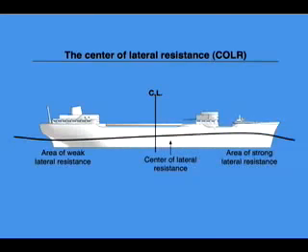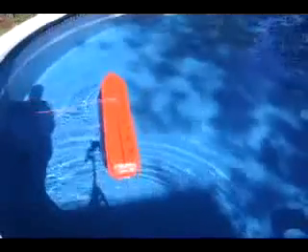This is mainly due to the positive pressure built around the bow in the forward motion, which creates a more resistant surface for the hull to lean on when pushed sideways. For practical ship handling purposes, it seems that the shift of the center of lateral resistance due to the speed is rarely more than 10% of the ship's length in the direction of the ship's movement.